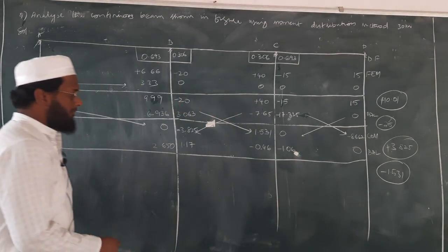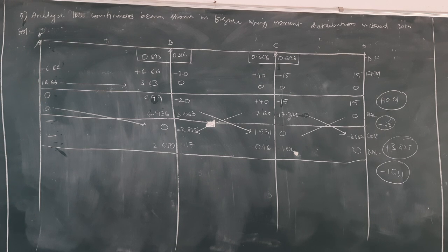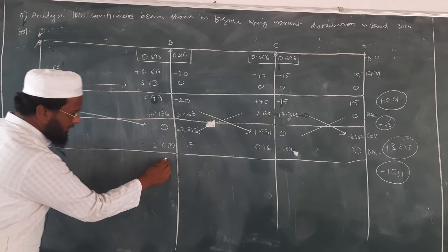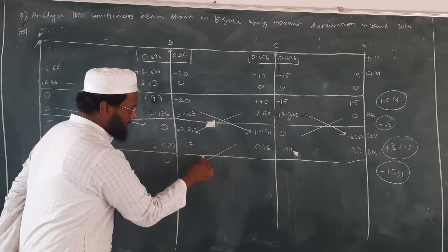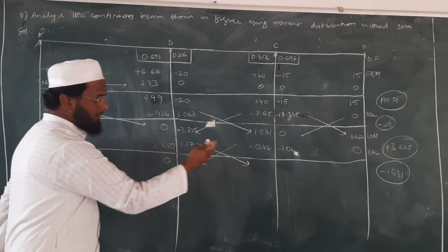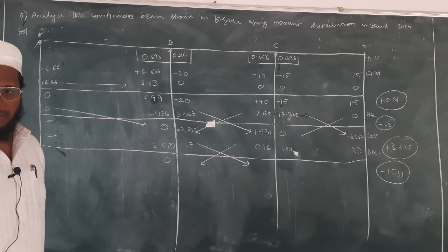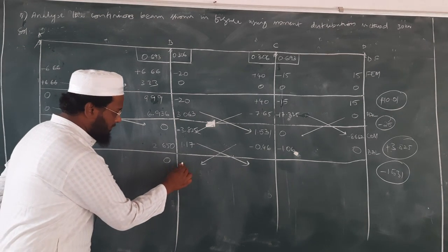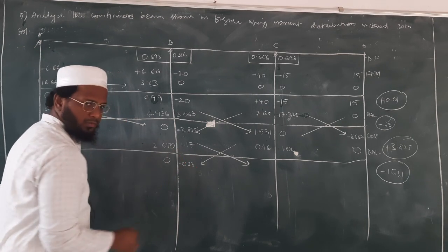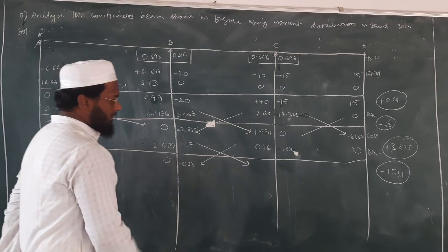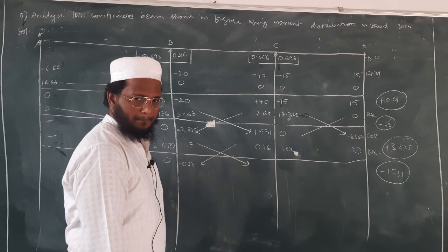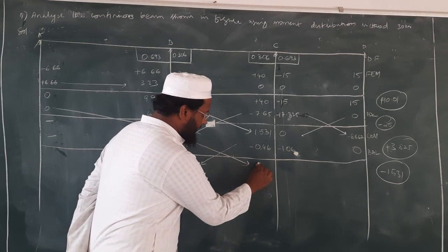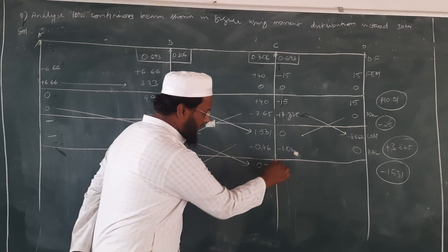After balancing, you draw the line for the simplification. You draw the line and carry over moments. Okay. Shall I send this value here? No, I can share this value. 0. What about this one? 0.46 divided by 2 is minus 0.23. Then here 1.17 divided by 2 is 0.585.